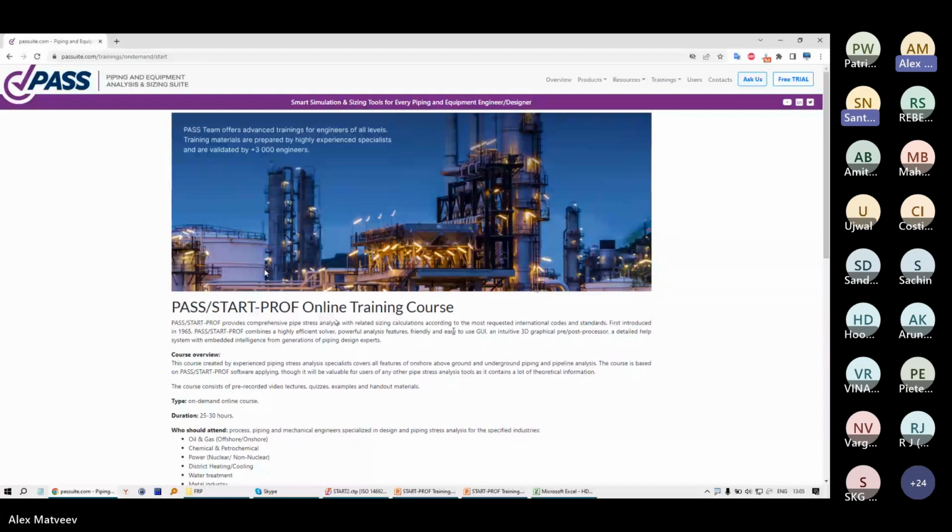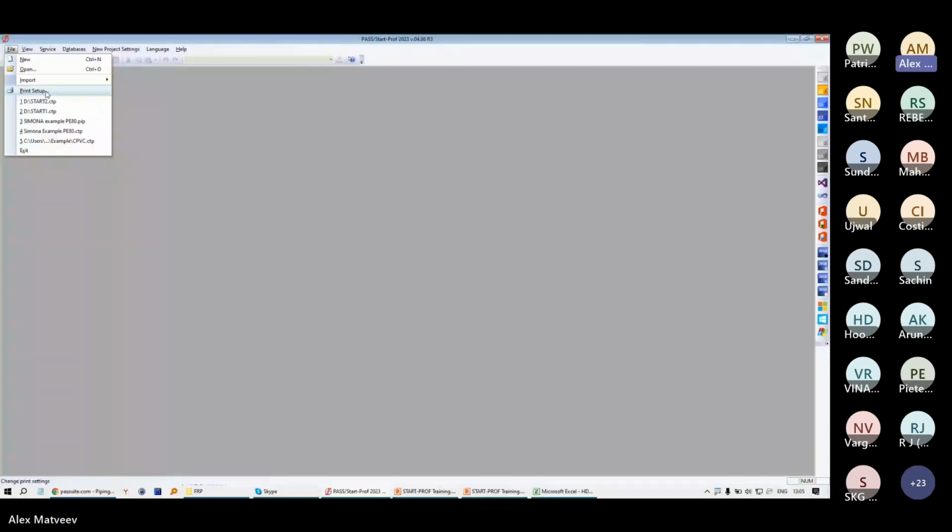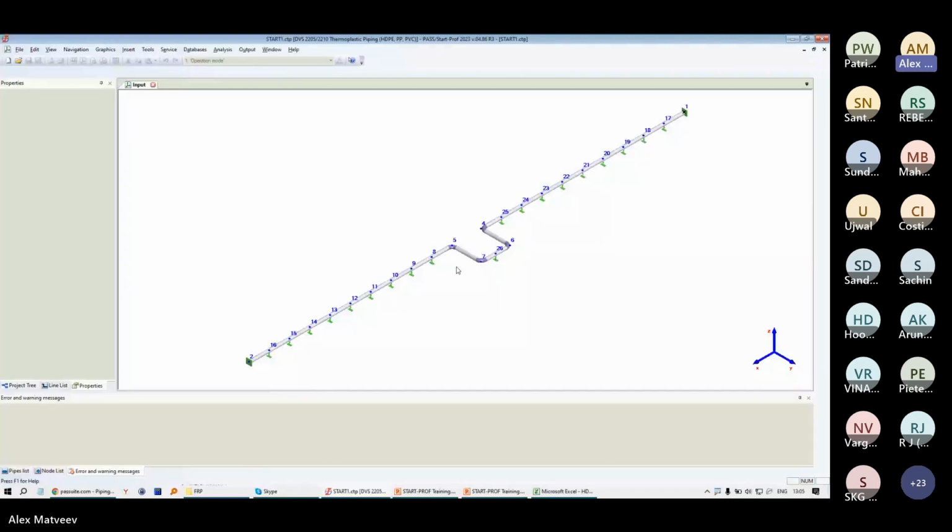Okay, so let's see. There are a few more questions. Yes, I see we have more questions. What about the stress analysis of HDPE piping? Actually, in START-PROF, you can select the HDPE piping. Let me show you. I will select the first file that we created. Here you can specify the PE 4710 material, for example.